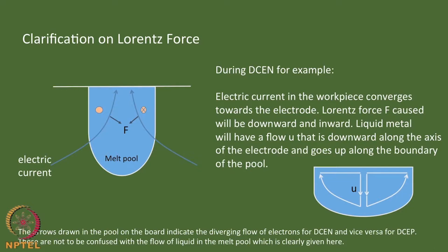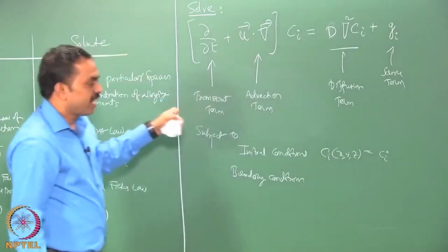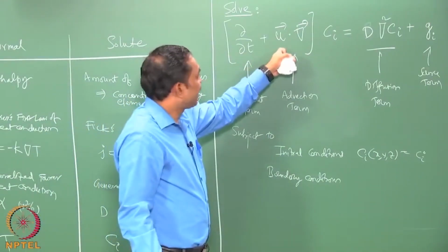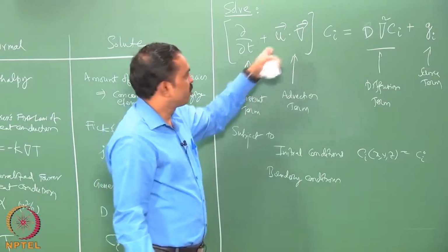okay, as an example I am giving you how it would change whenever you change the polarity, electronegative, electropositive, for a simple fluid flow situation here. So, which means that as often as you change the polarity, that often the convection is going to flip its directions. So, in other words, this variable u which is coming into the term here is going to be varying very often with the time, and is also going to be very strong.